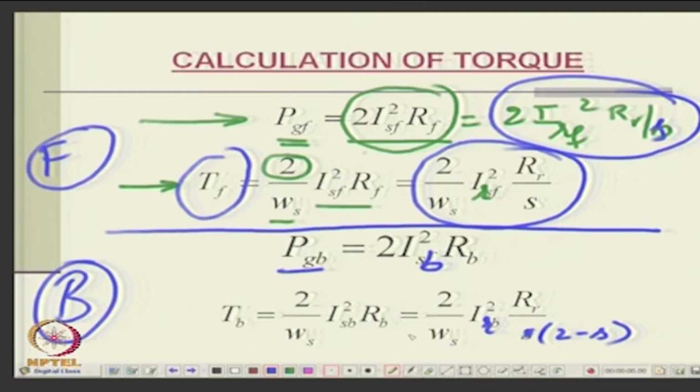Because it's a 2 phase machine, because it is all twice, isn't it? Hasn't that been taken care of in the earlier calculations in the model problem? No, it is reflected in the equivalent circuit. The equivalent circuit is taken as we have taken half of IM plus IA dash. You see, it is per phase. ISF, ISB are the per phase currents of the 2 phase model. Okay.